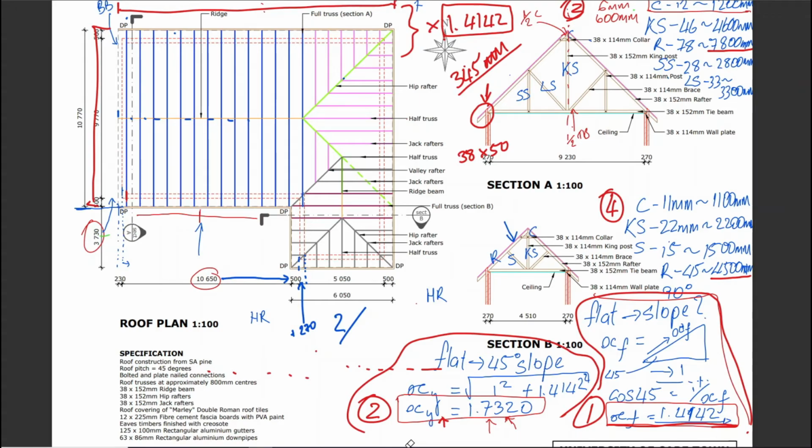find out which ends, how long is this distance? How much of it is exposed? And there are two ways of doing this. The first way is to scale it, and it's the faster way, by the way, so I'm sure you'll be interested to hear this. You could scale it from the furthest point to the furthest point, and then apply your factor, which was this one, X factor. That's the faster way.